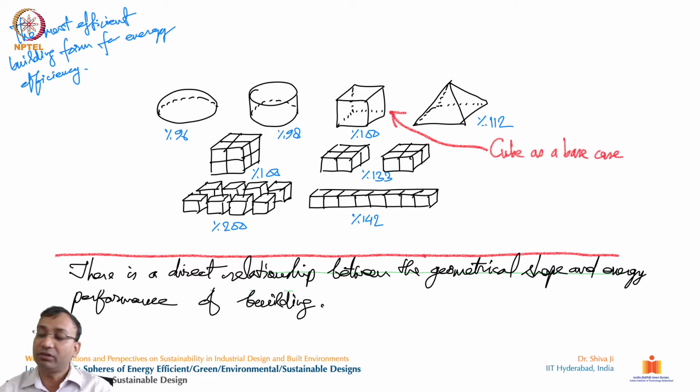So you can see with this illustration that, depending upon the form, shape, size, and scale of the building, the energy requirement of the building changes. While designing, how responsible and cautious we are about decisions based on the form and shape of the building is very important, because the energy consumption of the building is going to be there for all of its life on a daily basis.